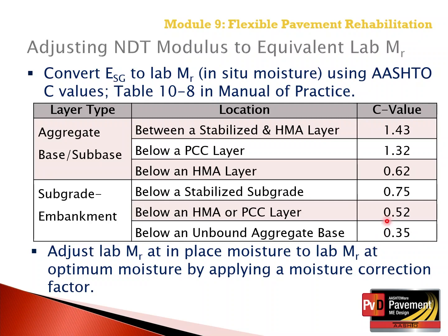So the C factors, or the C values, are used to adjust the back-calculated resilient modulus at the in-place water content to a laboratory equivalent resilient modulus by applying these correction factors.